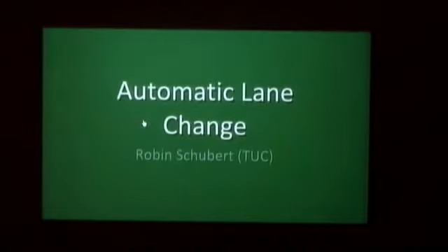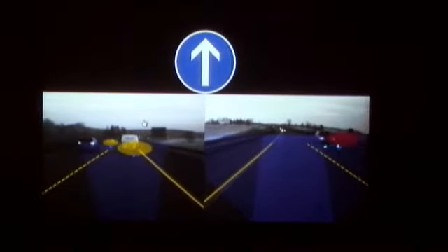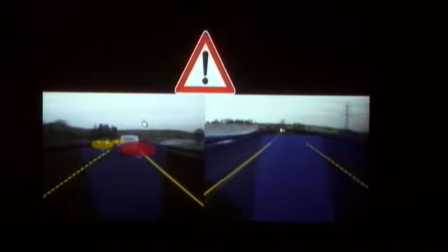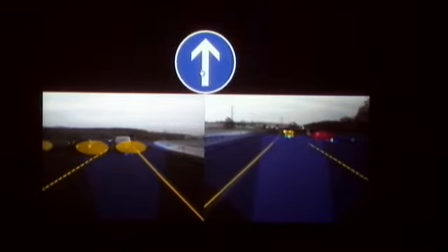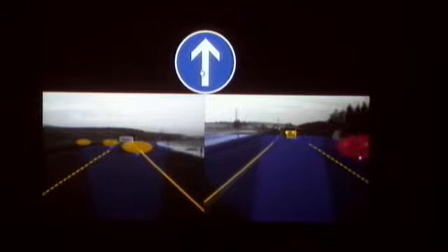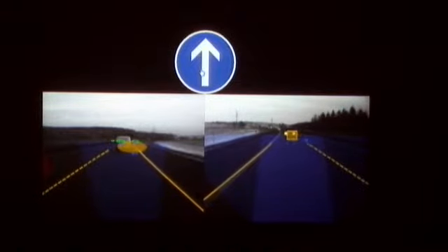At the beginning, a vehicle is overtaking us, and when this vehicle leaves our sensor field of view, we get a recommendation of lane change left, because we have a vehicle in front of us within our safety margin. We don't do this lane change at the moment, we are waiting, and another vehicle coming from behind changes this recommendation to keep lane, which is kept during the rest of the video.